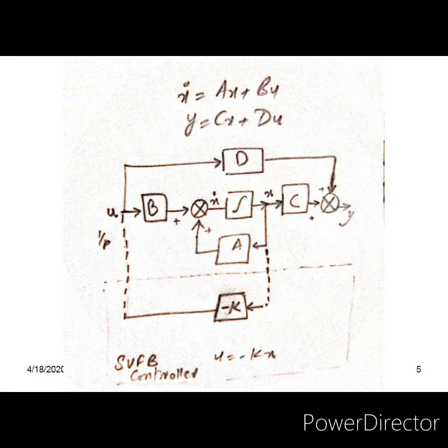Now the problem is that we have a system which is shown here in this slide in the form of a state variable model. The derivative of x equals Ax plus Bu. x is a state vector. It contains x1, x2 up to xn. n is the order of the system. n is the number of the state variables. n is the number of rows in the state vector.